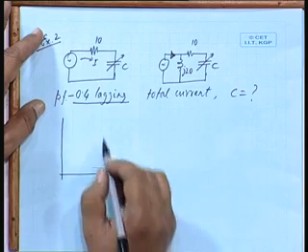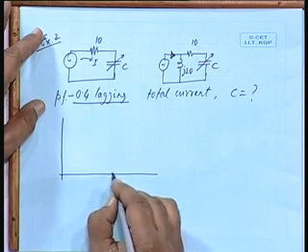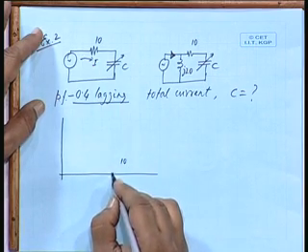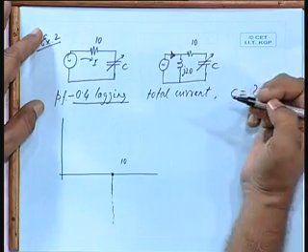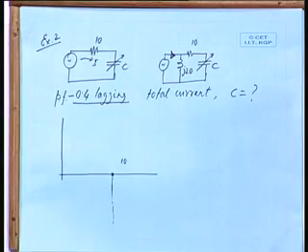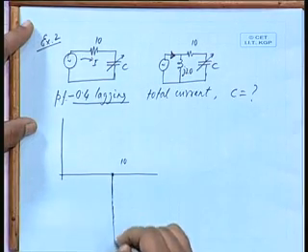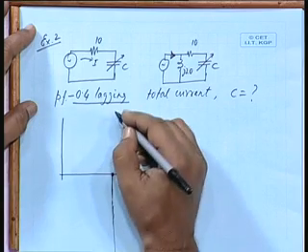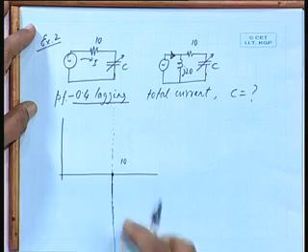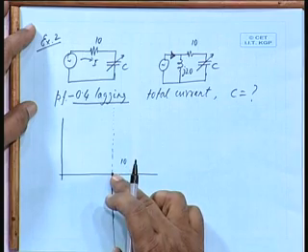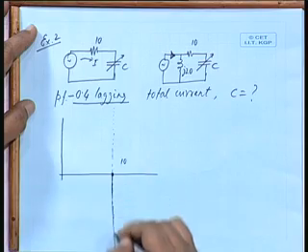All right. R is fixed, 10 ohms, C is varied. So, XC is varied from 0 to infinity. If it is not specified, then the variation can be over the entire range. So, this will tend to infinity. So, this is the straight line, of which only this is the relevant portion, because x is not varied from plus infinity to minus infinity, it is from 0 to minus infinity.